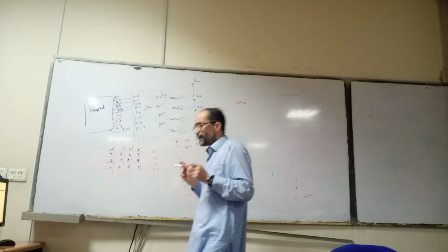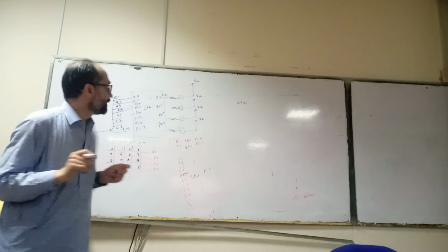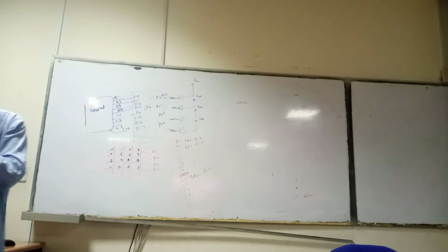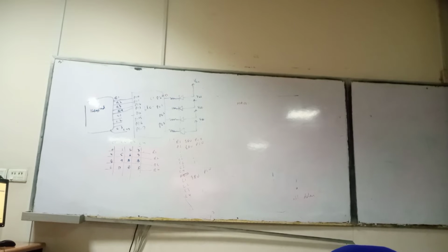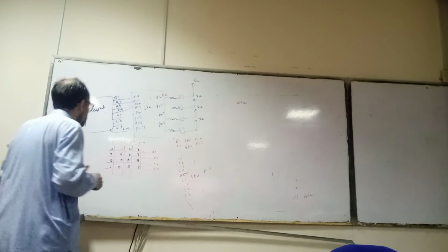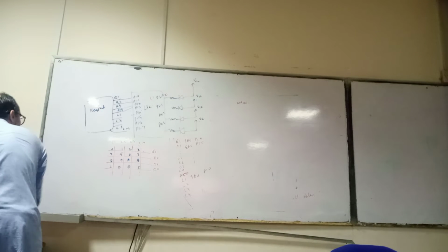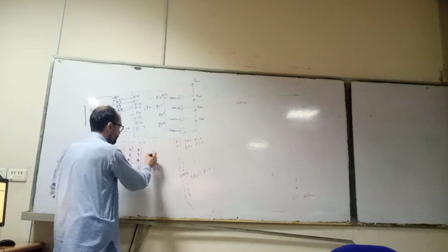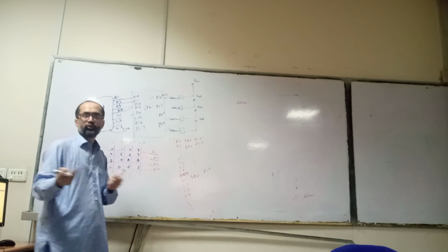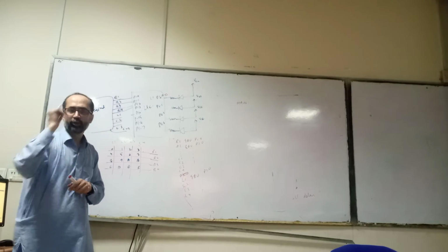Whenever you want to connect this keypad with the microcontroller, first you have to drive the rows, then scan the columns. Drive the rows and scan the columns. This is called a raster scan, some kind of scan mechanism. I will explain this with an example. Actually we can also do it the other way around: driving the columns and scanning the rows. Now in this case we assume that we are driving the rows.